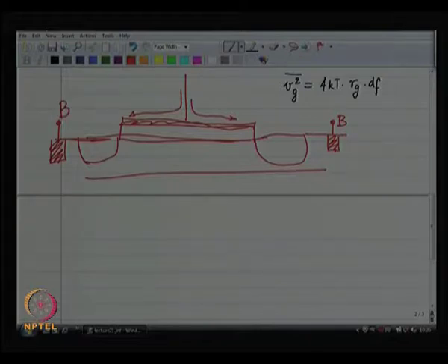Suppose you have put a ring of body contacts around your transistor. That is called a guard ring, just by the way. It is good to do that because that reduces your substrate resistances, we will see how. So, the body sees a resistance which is marked by the resistivity of all of this. It is a distributed resistance.